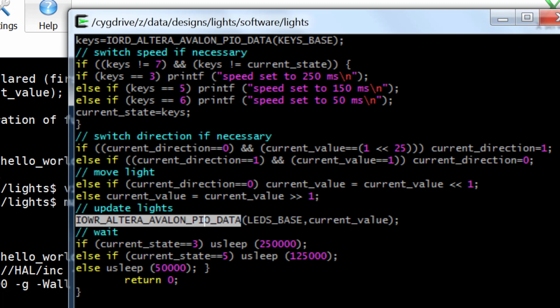So let's say I want to put a digit like 9 on there. The first segment on the top is bit 0, the least significant bit. And then you go clockwise around. So that's 1, 2, 3, 4, 5, and 6. Those are your bits. So if I want to do a 9, actually some people find this confusing.